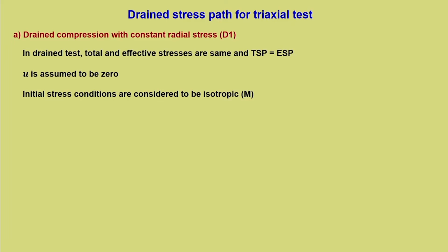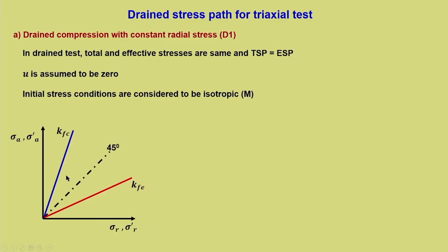If we want to create anisotropic consolidation, that is also possible, but we are going ahead with the simple initial isotropic stress condition. Now we are plotting all three stress paths, but later you will see that we will adopt any one of these as and when convenient. It can be t-s' or q-p' plots. So, let us first start with the sigma A', sigma R' plot.